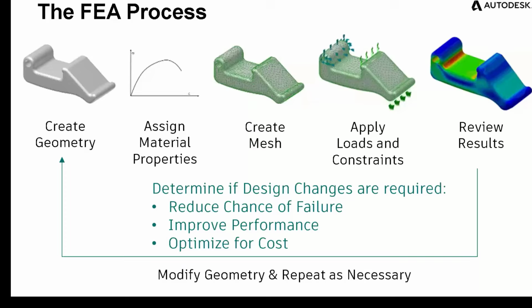And many times when we get callbacks from customers that, hey, the results don't match the shop, the first question I'll ask is, okay, does your computer material match your shop material? Well, we think so. Okay, you need to know so. So that's where you need to involve an outside lab, analyze your current material, find out what the calculated Poisson's ratio and Young's modulus and densities and things are of that material, and then plug that into the software. If you don't get that right, nothing else is going to be right. Then you step on to the next process.